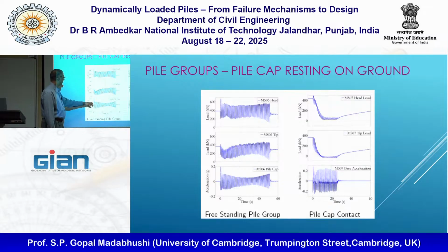Pretty much similar level of acceleration. In most liquefaction problems, input motion is actually not that important. Once you hit anything above 0.1 g, the soil will liquefy. And whether you play nice swaras in music, or sing different ragas, the soil doesn't really care.